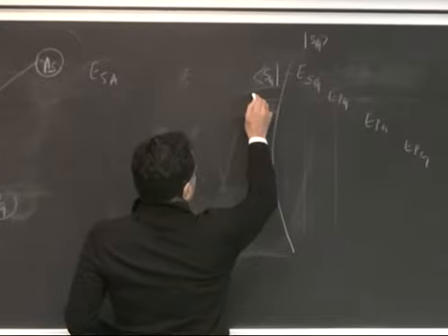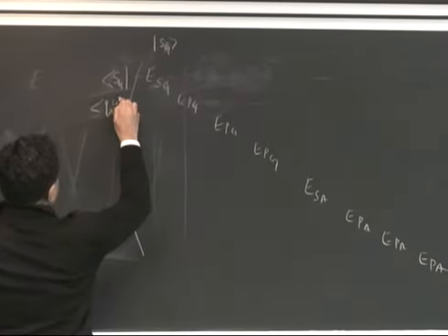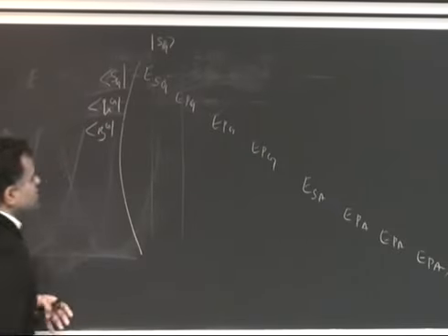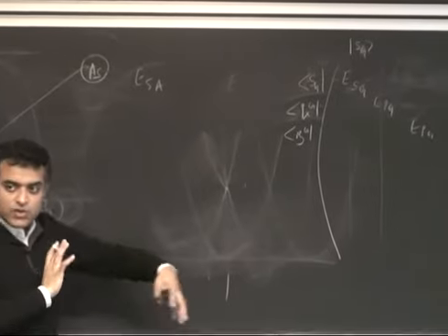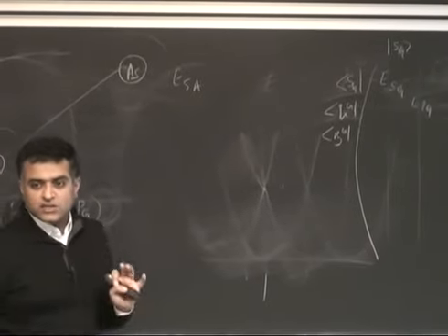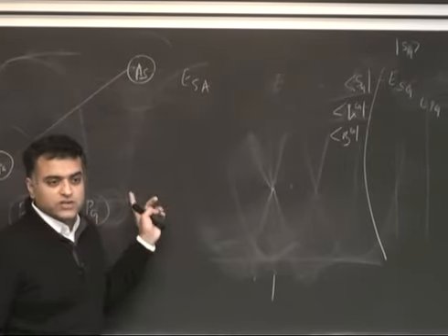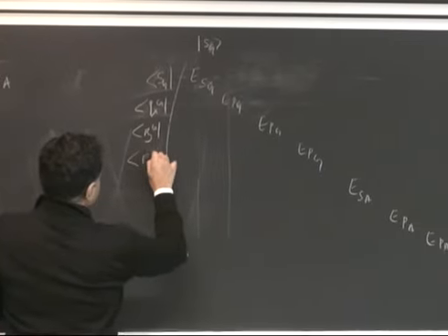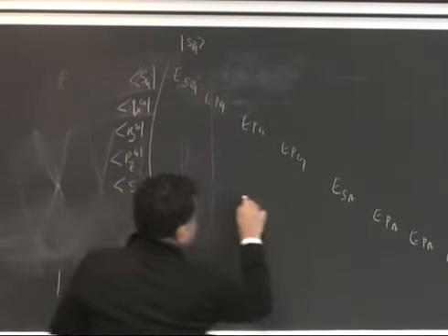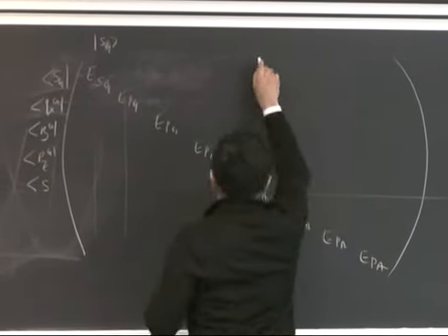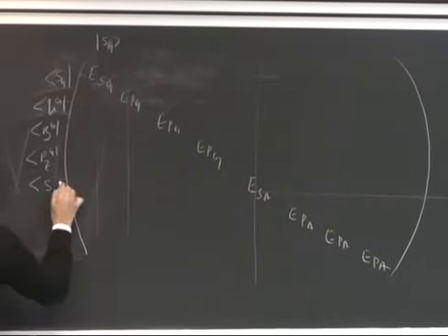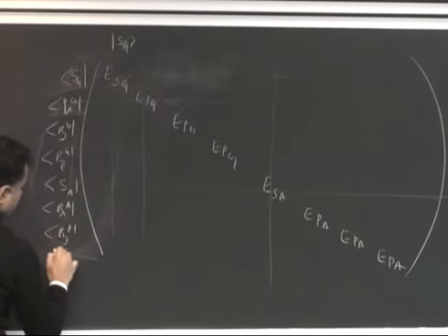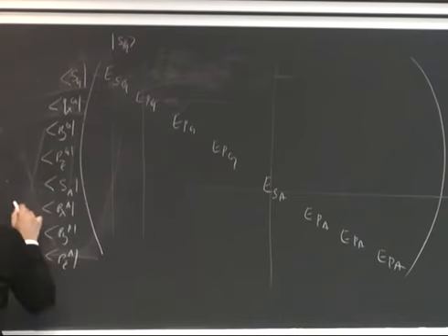And similarly, you can call it Px of gallium, Py of gallium. The reason I'm labeling it x, y, z now is because the moment you allow for hopping and bonding, the orientations matter a lot. The angles, the geometry matters very much, and we are going to see why now. But before that, it doesn't matter at all. So Pz of gallium. Similarly, S of arsenic, Px of arsenic, Py of arsenic, and Pz of arsenic.